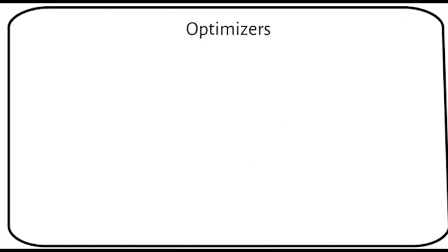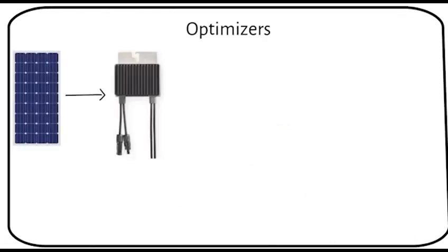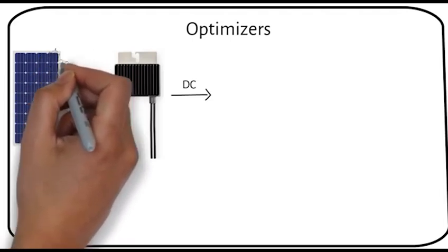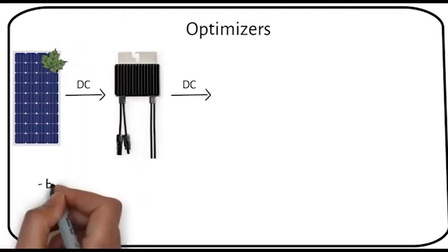A power optimizer is a device that, while not an inverter in itself, is important enough to mention in the list. It's a technology that combines the best features of microinverters and string inverters. Attached to individual solar panels, power optimizers adjust the DC power using a method called maximum power point tracking. This process enhances the panel's output, ensuring that issues like shading, dirt, or panels facing different directions don't affect the overall system's performance as much.